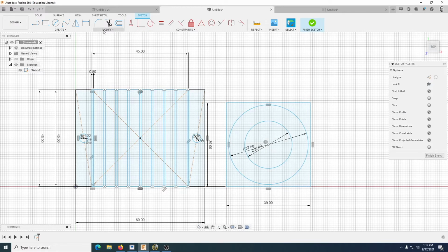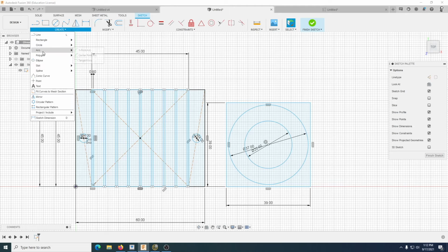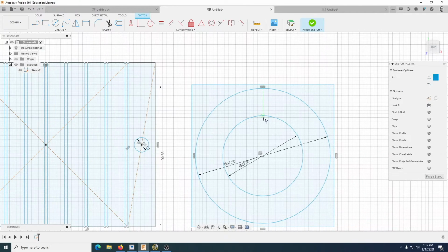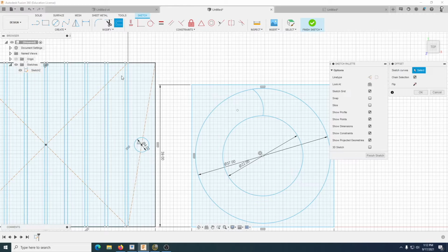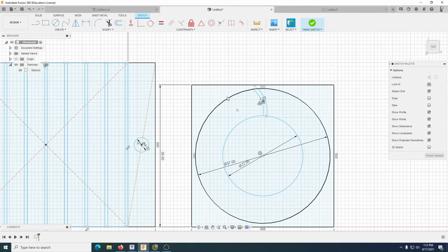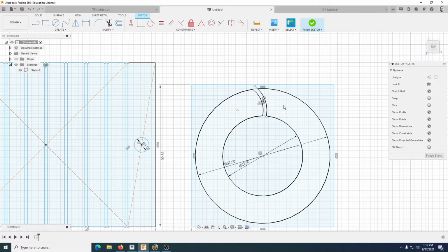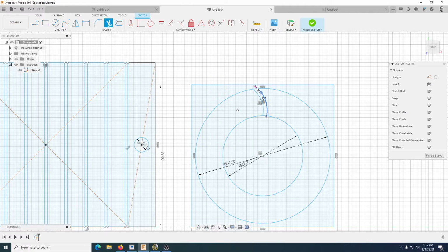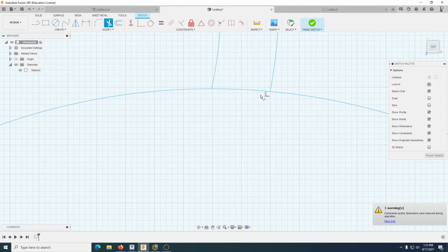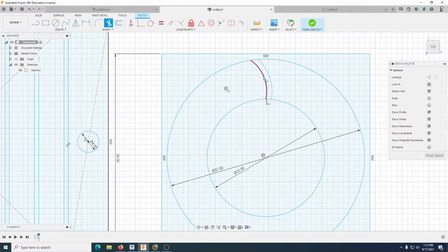Okay, so we can actually do the blades. So to do that, I would just draw a 3-point arc. Just zoom in a bit. We go here and there and come out. I then offset that from there to there. It's a bit thick, but because it's not actually working, that seems to be okay. I'm going to press the letter T. That's the scissors over here, so shortcut key again, and just trim that and that. Okay, so now everything should be joined.